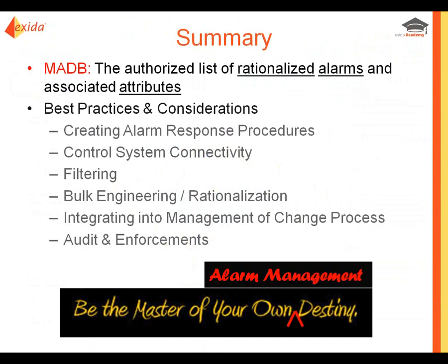We talked about how to integrate the master alarm database into the management of change process, so it's not a static database that's used initially just for development. It's really a critical part of your alarm system and maintaining it over the life of the control system. So it should be part of your management of change process. And to support that management of change process, it's recommended to do comparisons every so often of what's in your master alarm database, the settings there, versus what's running in your control system.